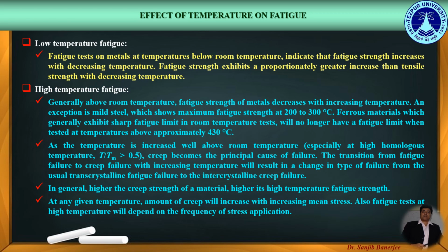We will now study about the effect of temperature on fatigue. Let us first study about the low temperature fatigue. Fatigue tests on metals at temperatures below room temperature indicate that fatigue strength actually increases with decreasing temperature. Fatigue strength exhibits a proportionately greater increase than even tensile strength with decreasing temperature.